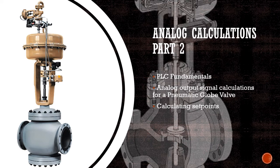In this particular presentation, what we'll look at is a pneumatic globe valve that uses a 4 to 20 milliamp signal to control the air pressure, and then the air pressure pneumatically opens and closes the globe valve. We will be looking at calculating the set points. So, given a percentage of open or closed of the valve, we will then calculate the necessary signal from the PLC and then the necessary required PSI air pressure to control the valve. So let's get on with it, shall we?